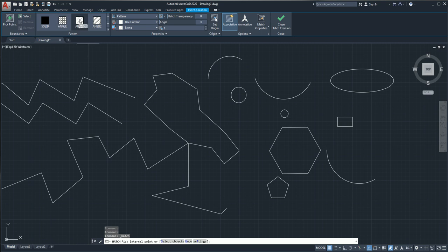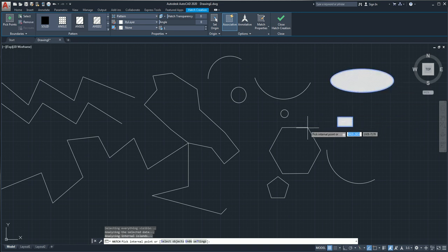So let's click on this hatching pattern and just click the boundary we want to hatch. It should be a closed boundary. We couldn't hatch in the space or in the air right there. This is an open boundary, so nothing will be hatched. We should have a closed profile, a closed boundary, like this one.